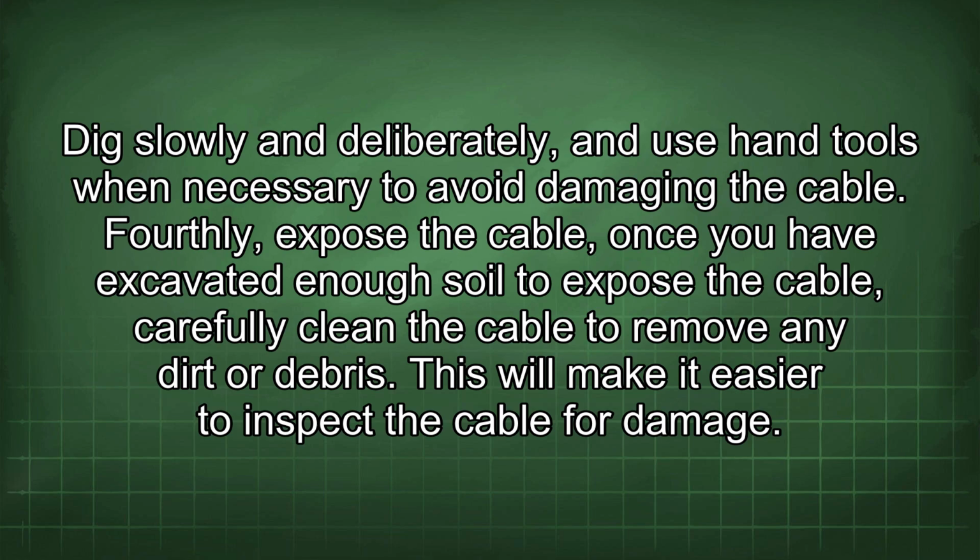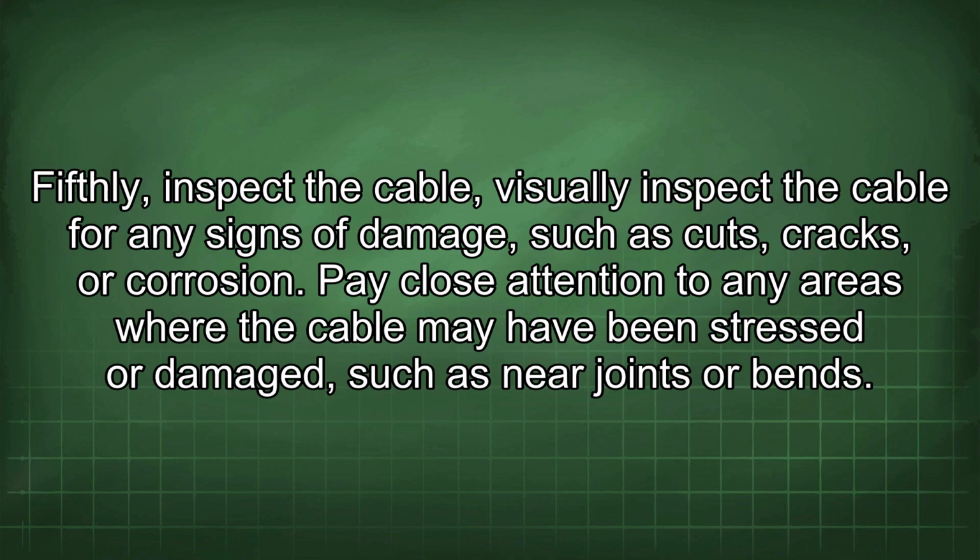Fourthly, expose the cable. Once you have excavated enough soil to expose the cable, carefully clean the cable to remove any dirt or debris. This will make it easier to inspect the cable for damage. Fifthly, inspect the cable. Visually inspect the cable for any signs of damage such as cuts, cracks, or corrosion. Pay close attention to any areas where the cable may have been stressed or damaged, such as near joints or bends.